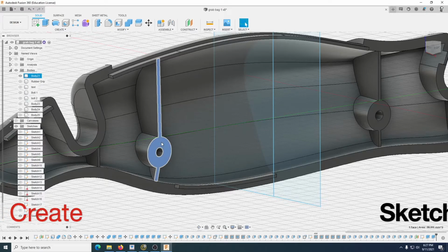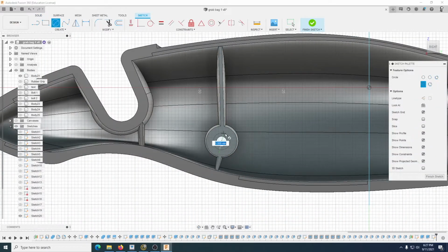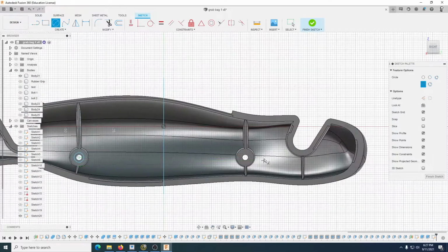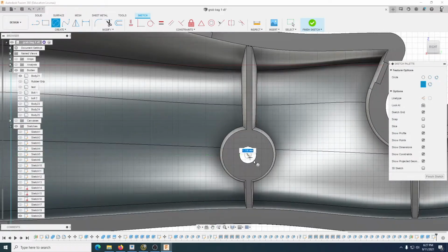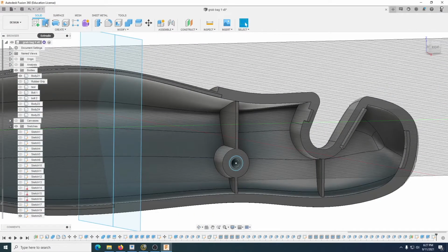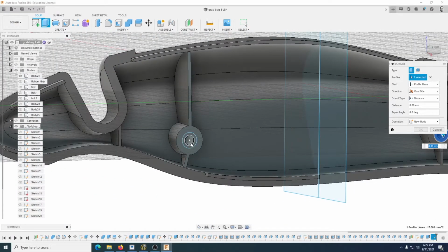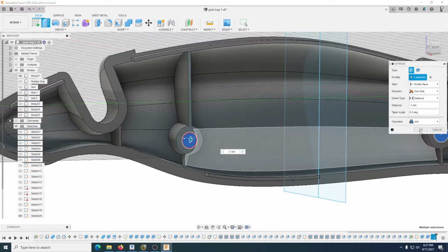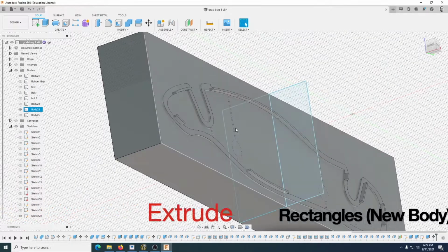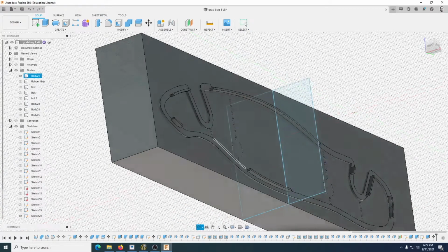Okay, so go here, right click, create sketch, C for circle, put that there, and again don't forget we can always delete things like this later. Finish the sketch. We'll do that, and that just to make sure. We're going to go -1, okay, and we are actually going to join this one. Okay, so join. Now there shouldn't be anything separating, joining the inside of this to the outside of that, theoretically.